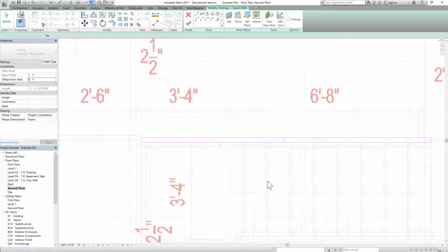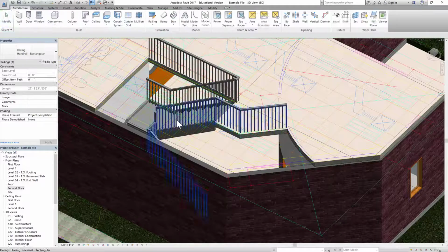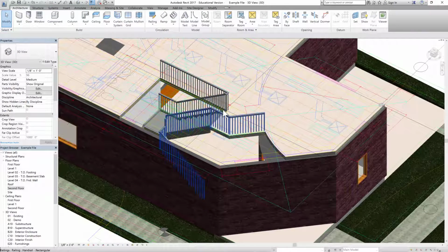from here to here. So what you want the railing to do is climb up, turn on the second floor, and join this wall that we'll be modeling later on. Click OK. And in 3D, as you can see, that railing has been modified. So it's climbing up and it's going back and will join that wall once you model it. So this is how you will actually model the next floor and create an opening and adjust handrails if needed.